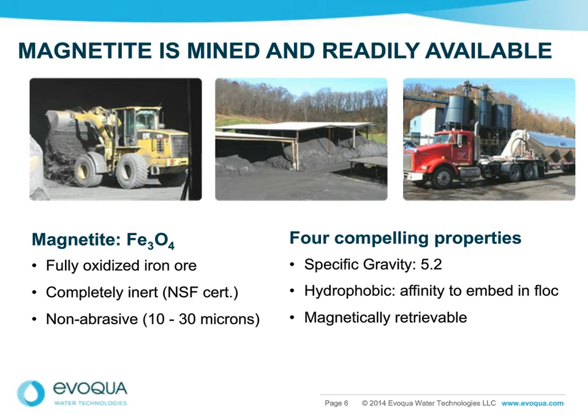Now, because it's charge neutral and chemically inert, it's actually hydrophobic. And what that means is it doesn't fit well in the water polar matrix, and it readily gets attracted to solids that are in there and gets embedded in those solids and increases their specific gravity to about 1.2, 1.3. It's pretty inexpensive, about 30 to maybe 50 cents a pound delivered anywhere around the world.